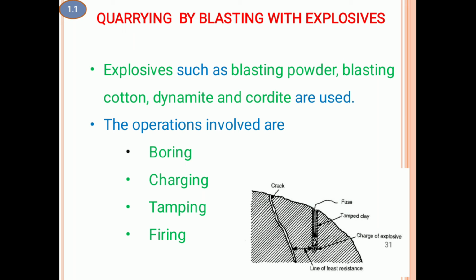drilling a hole, boring in the rocks, hard rock. It will be about a 1 inch diameter hole, or it may be a 2 inch diameter hole, based on the intensity of the blasting, right? So initially a boring hole will be made. It will be about 3 feet or 4 feet or something else. Next you have to charge it. Charge is nothing but putting the explosives inside.